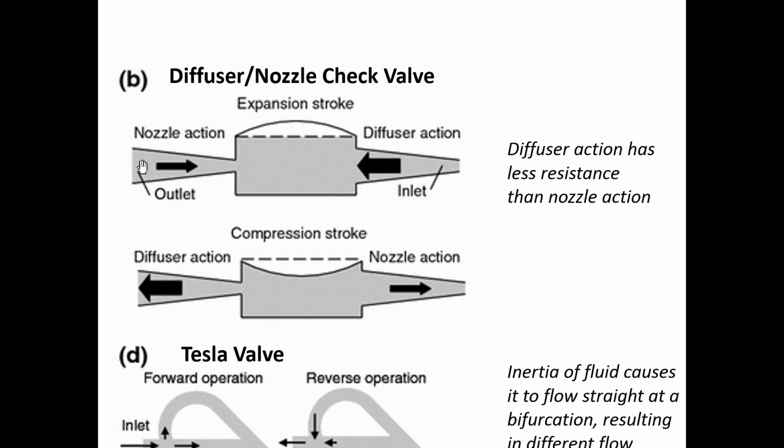Notice that these two channels are actually the same dimensions. The only difference is the large end. These two ends are mirror images of each other. But the inlet, the large end, is connected to the chamber, and for the outlet, the constricted end is connected to the chamber. So these two triangular shaped channels present different resistances whether you're going in one direction versus the other.